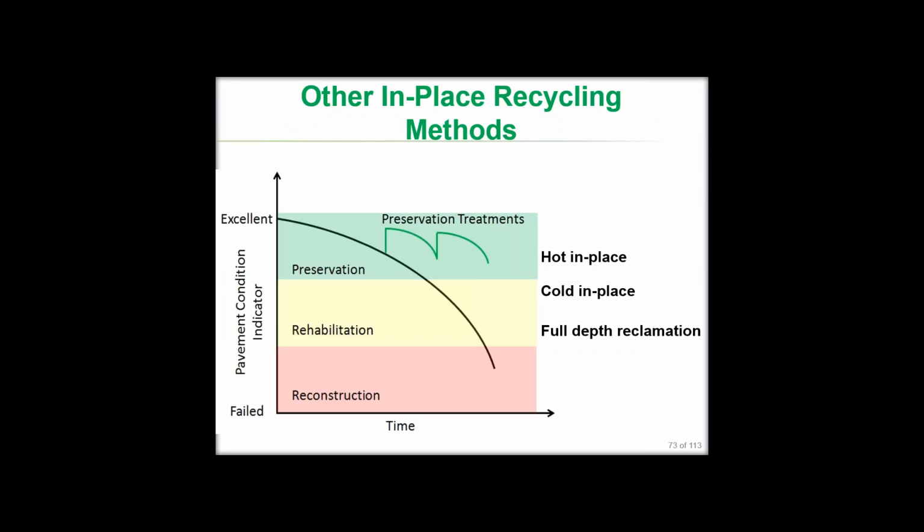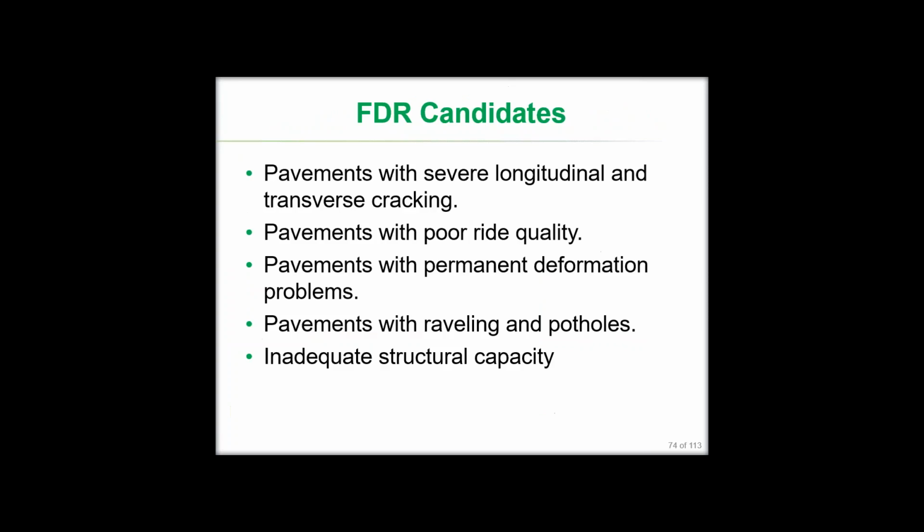And just to give you a timeline of different activities which was discussed at the beginning of this webinar, we have various other in-place recycling techniques which are hot in place, cold in place, and full depth reclamation. And full depth reclamation is the one that is usually conducted when the pavement approaches its terminal service life.